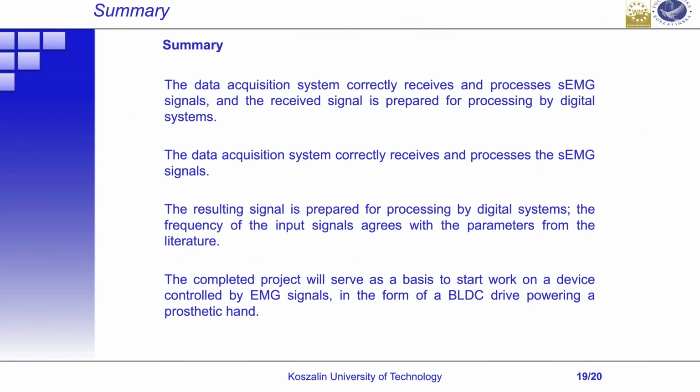This work presents the design of an analog processing circuit for collected data. The performance of this task began with designing a pre-gain module using commercially available instrumentation and operational amplifiers. The high-pass filter, full-wave rectifier, low-pass filter, and calibration gain circuit were designed similarly. At each stage, the characteristic parameters of the circuits were determined, and the waveforms of the shaped signals were presented, thus giving a complete insight into the performance of the analog processing module.